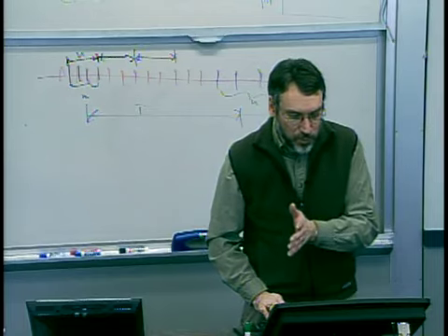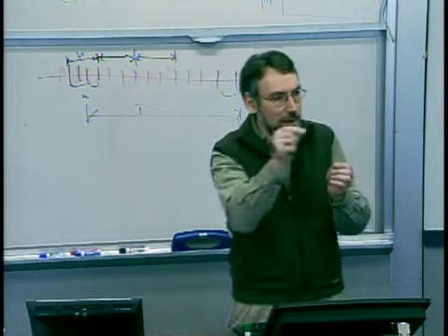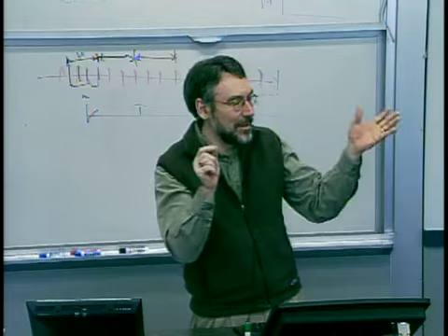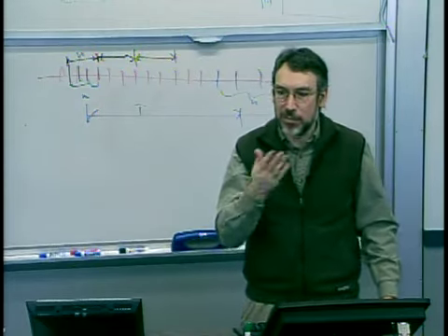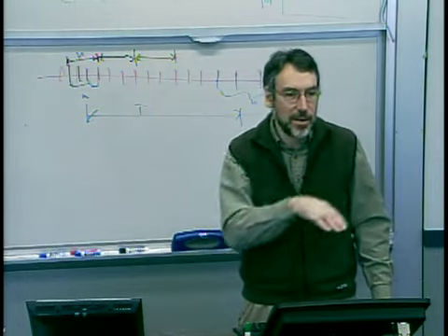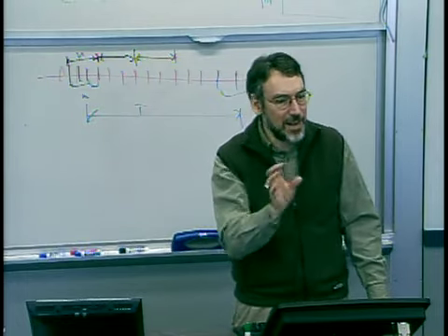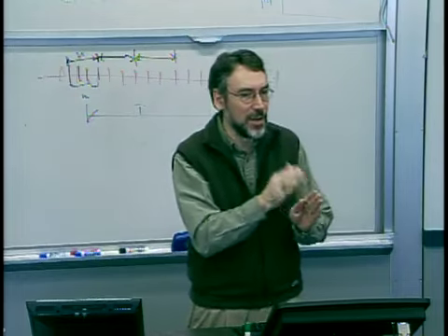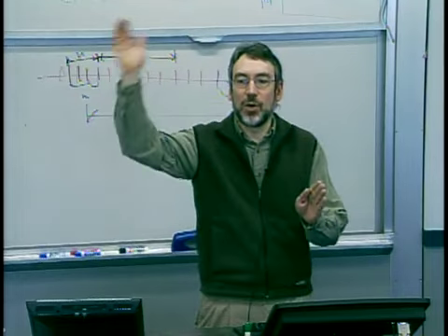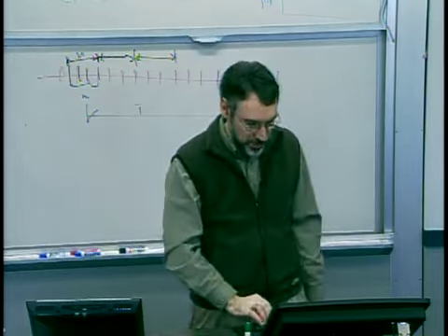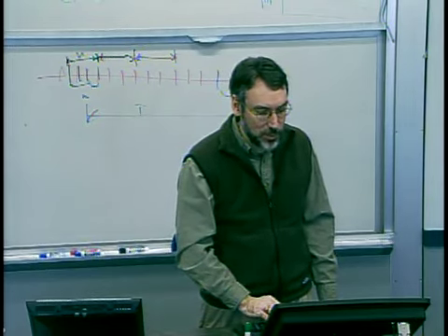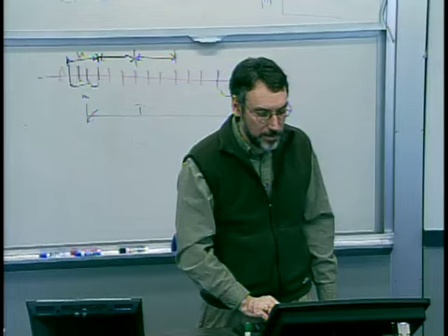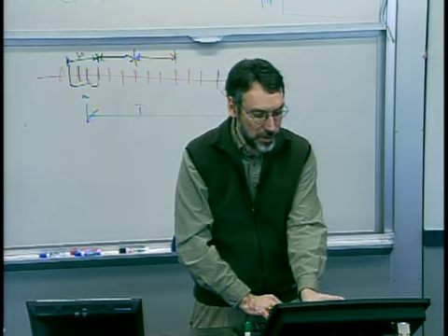If it were truly uncorrelated, each and every new data point is completely independent of the other. And the point is simply here that if you're sampling from some physical processes, there may be an inherent correlation that isn't the one you're trying to get at. You're trying to detect long-term trends and not detect very small shifts. And so you can play around with the sample time compared to the inherent correlation of the process.